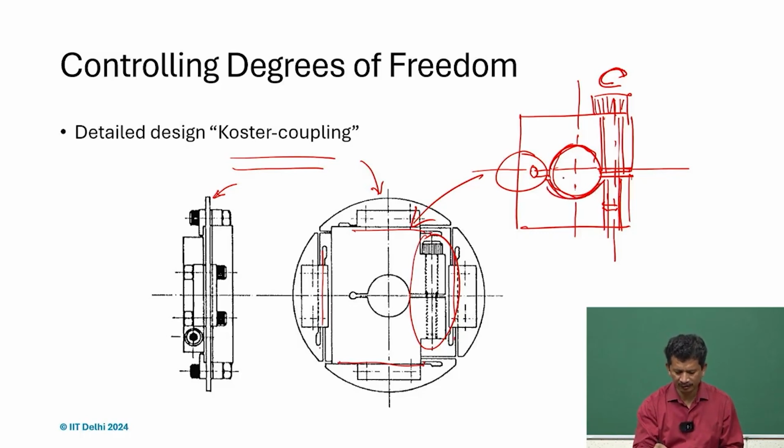It gets tightened, and this way you will not damage the surface of the shaft. It is also very easy to remove, because it is still within the elastic limit. If we loosen it, it will spring back, and then you will have the proper clearance and you can remove it.